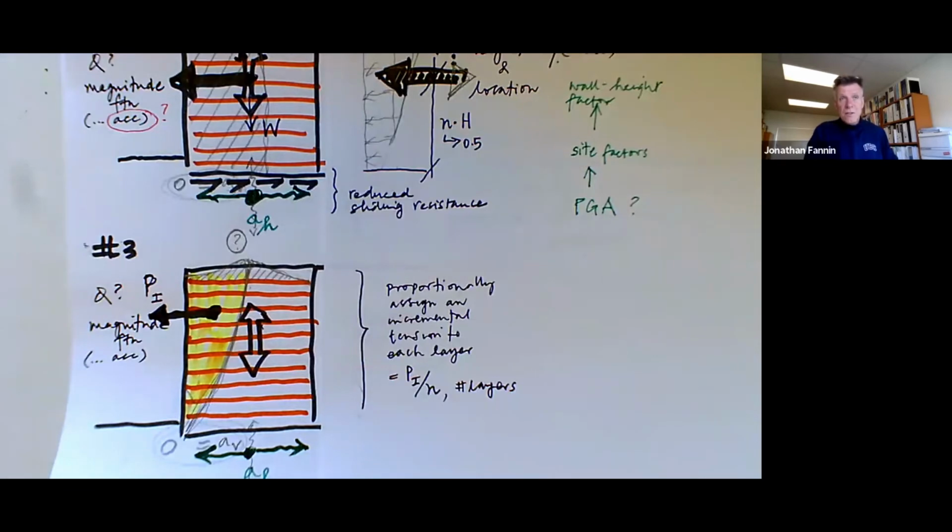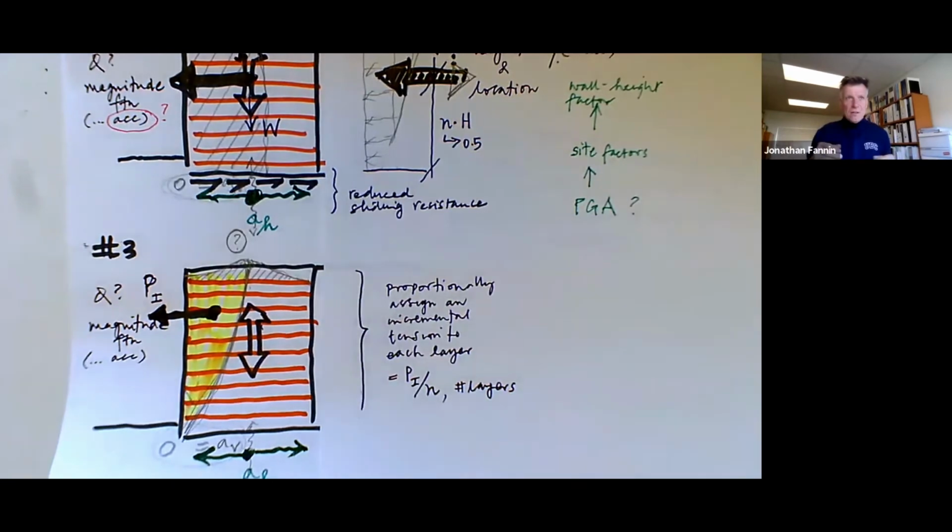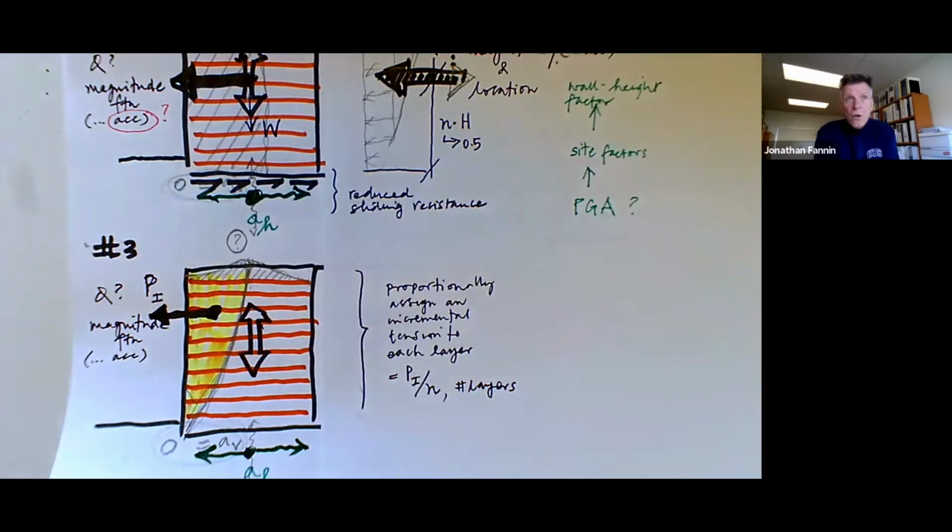And the geosynthetic reinforced soil structures that I visited, they come in all shapes and sizes. So Gabion facings, lock block facings, full height facing panels, and there are subtleties to those that we could speak to. But let me tell you what I took out of a day looking at these structures: from a point of view of internal stability, they were performing just fine.